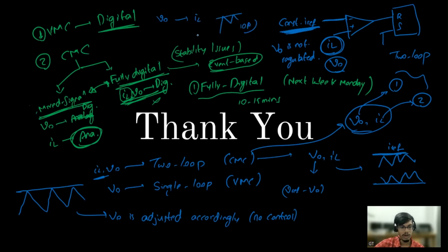Say I don't want inductor current to cross 10 amperes. I cannot do this in voltage mode control because I don't have control, right? I am not bothering about inductor current. Whatever the PID controller gains that I am selecting, that will generate the control voltage that will affect the duty ratio. So I am not controlling IL. If you want to control both, you need two loop control. You cannot do it with a single loop control.